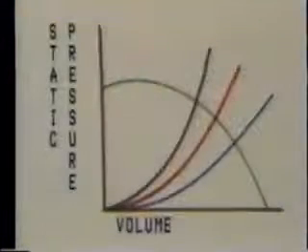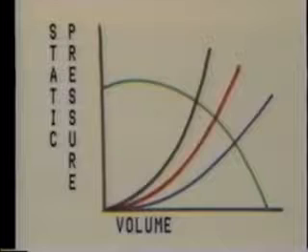Shown here is the effect of an inlet vane type system. The fan inlet vanes are positioned by an actuator in response to a signal received from the system's static pressure receiver controller. The static pressure transmitter, through the receiver controller and actuator, repositions the inlet vanes to maintain a relatively constant duct pressure at the point of sensing.